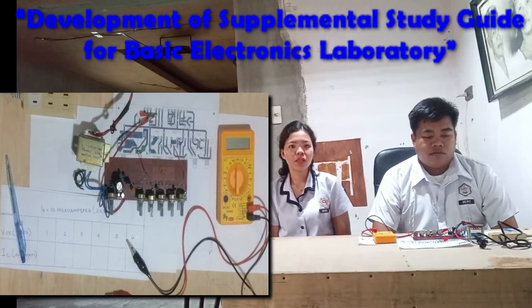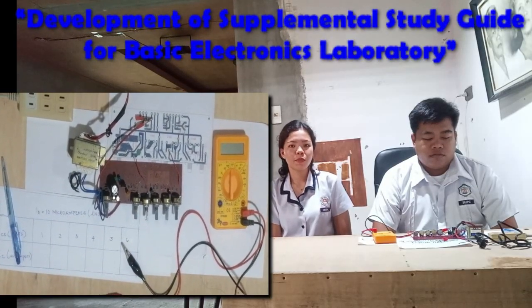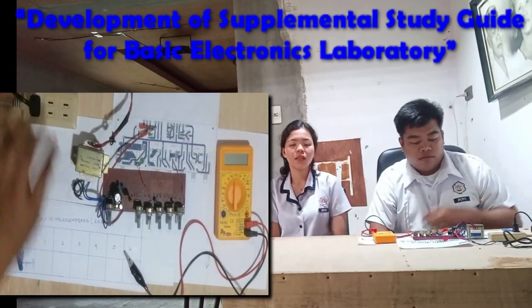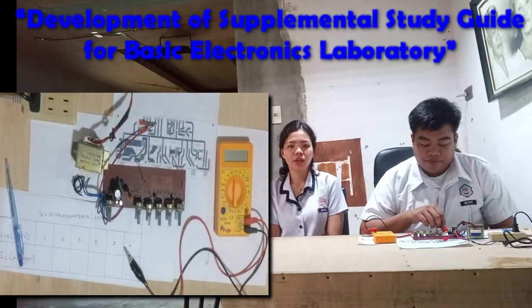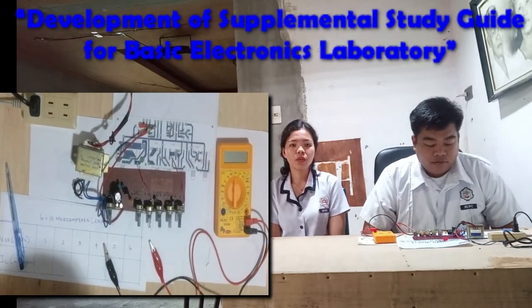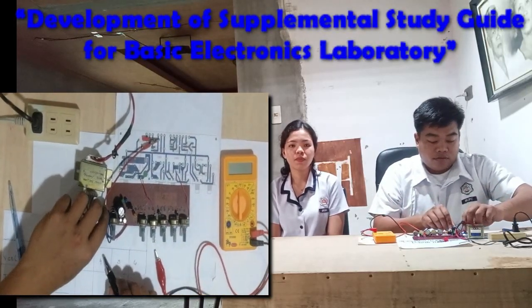And now, let's proceed to the step-by-step procedure of this experiment. First, plug in your power supply. Be sure that the unit is turned on. Second, construct the circuit shown in figure 3-1. Use the wiring diagram shown in figure 3-2. Turn potentiometer R1 for maximum resistance and set R4 to mid-range.